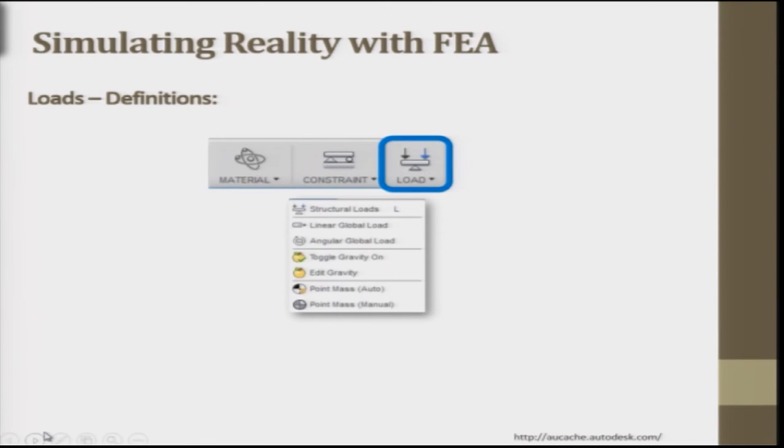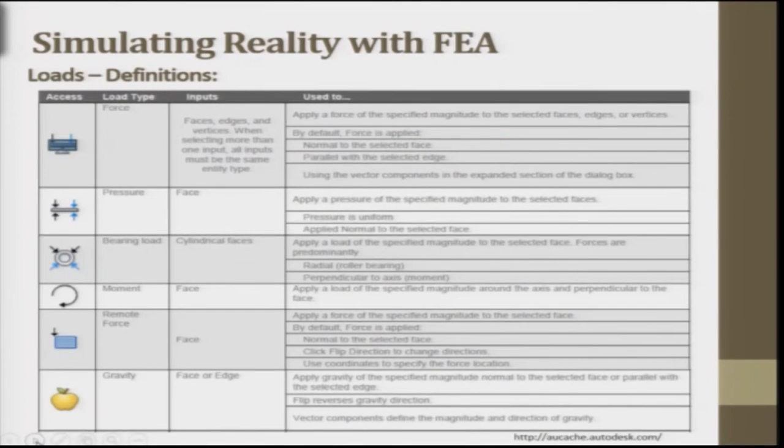Then is load. What kind of loads are to be put? Structural loads, linear loads, angular loads, toggle gravity, edit gravity, all these options are available. Then we put the specific loads. So, these are the load definitions. We can put force, pressure, bearing load, moment, remote force, gravity, etc.